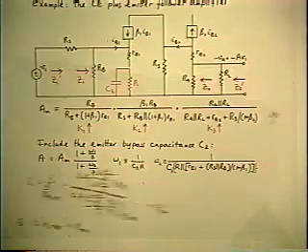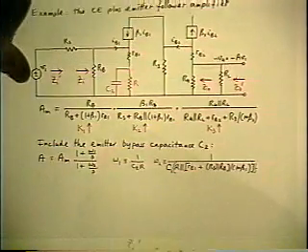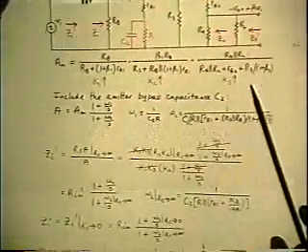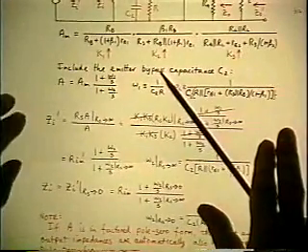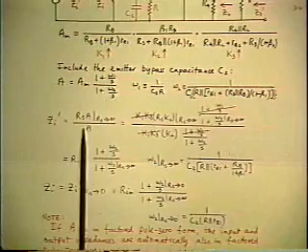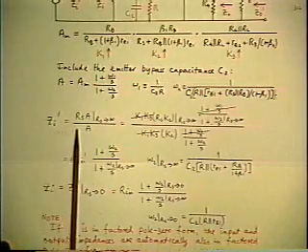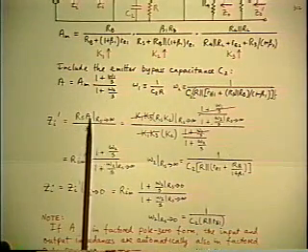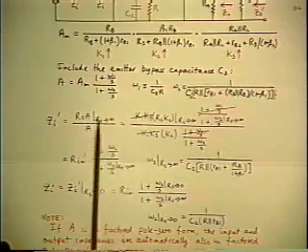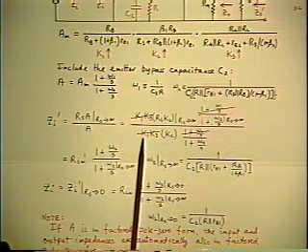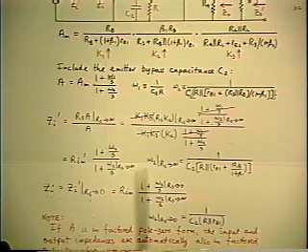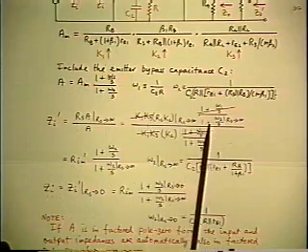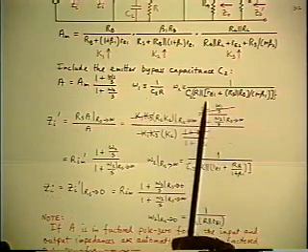So going back to the input impedance theorem now, starting with the modified gain, including the inverted pole and 0. Now we apply the theorem to the modified A, and again the midband part of it stays exactly the same. So we don't have to deal with the K factors again, we've already done it. All you have to do is look at the remaining factors and follow the same process.